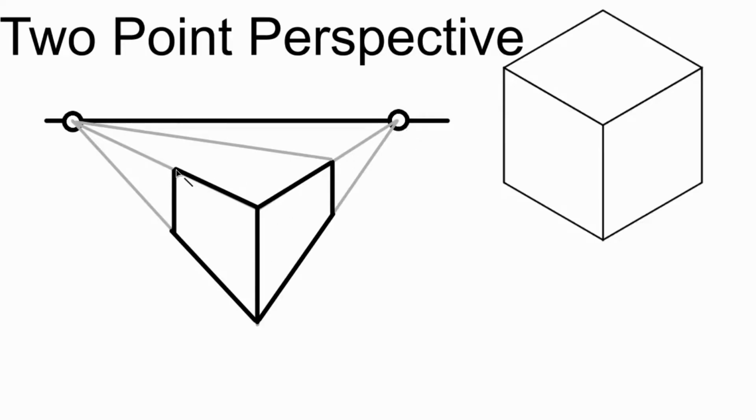So I just have this one corner here. It's going to go back to the vanishing point on the right because it crosses over our visible vertical line there. We don't worry about these two bottom corners. Even though we drew corners, we don't have to worry about them because those show the insides of an object. And if we look at our isometric here, we don't see those lines, so I'm not worried about them.